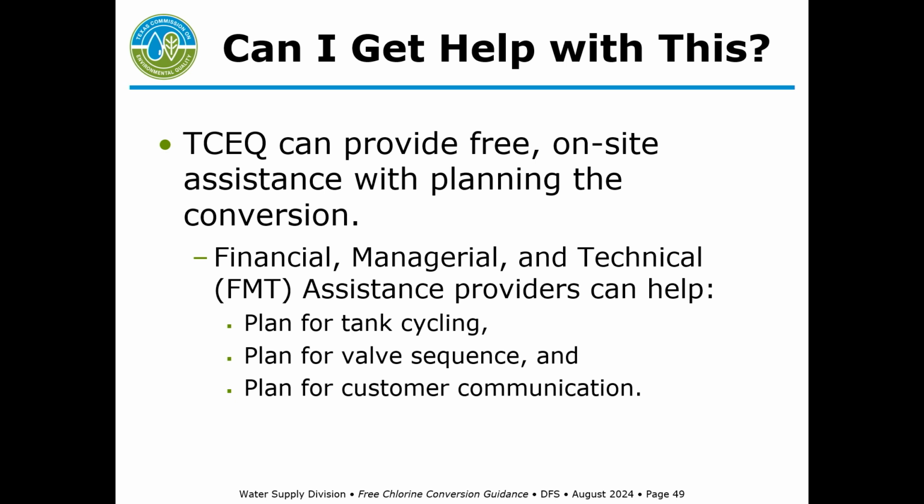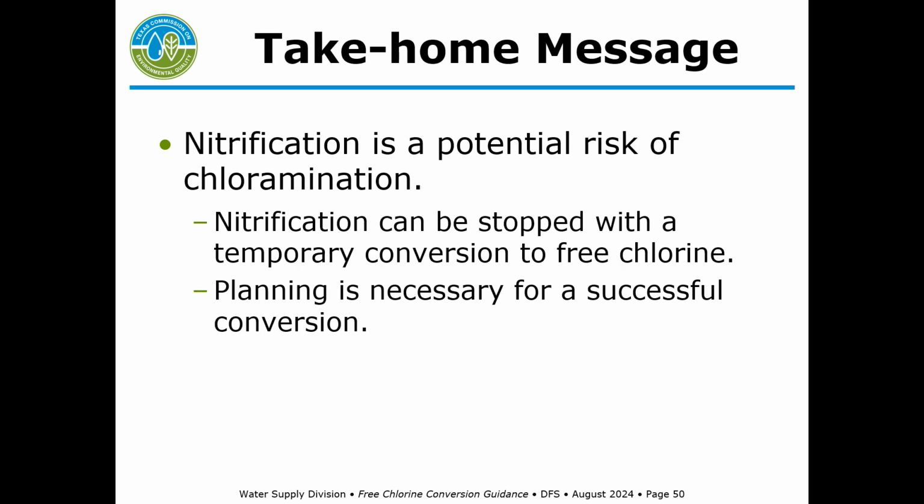They can help with tank cycling, valve sequencing, and a plan for working with your customers. Nitrification is always going to be a risk for any system that has chloramines in it. You can stop nitrification with a temporary conversion to free chlorine, but as I hope we all learned here, a lot of planning is necessary to make that free chlorine conversion successful.